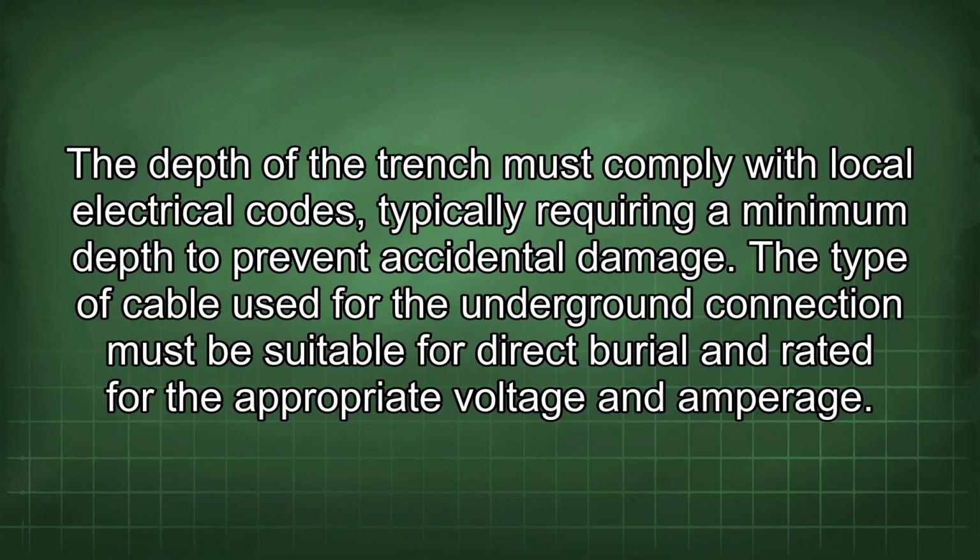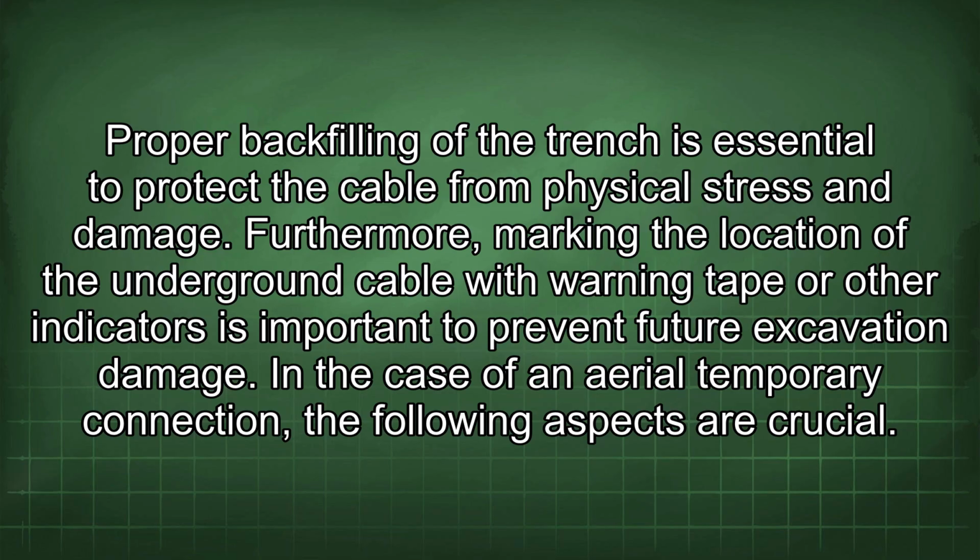The type of cable used for the underground connection must be suitable for direct burial and rated for the appropriate voltage and amperage. Proper backfilling of the trench is essential to protect the cable from physical stress and damage. Furthermore, marking the location of the underground cable with warning tape or other indicators is important to prevent future excavation damage. In the case of an aerial temporary connection, the following aspects are crucial.